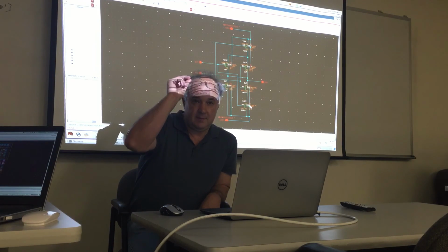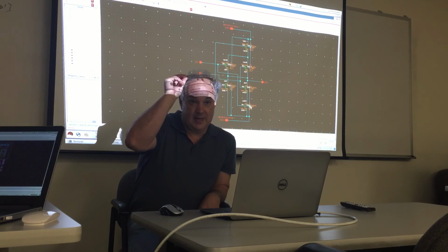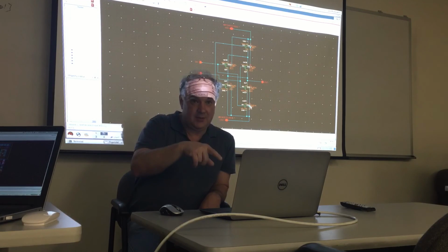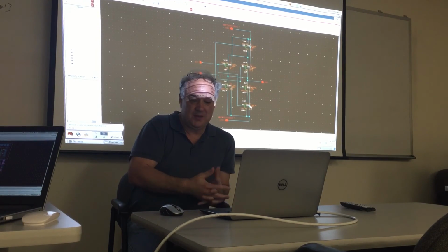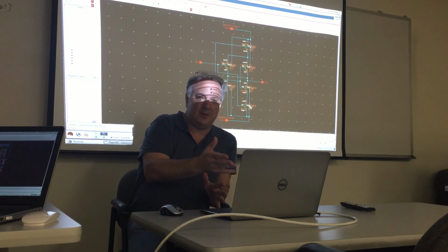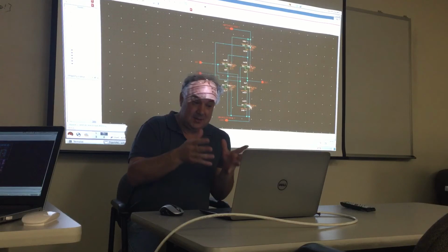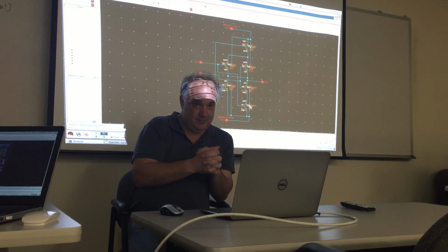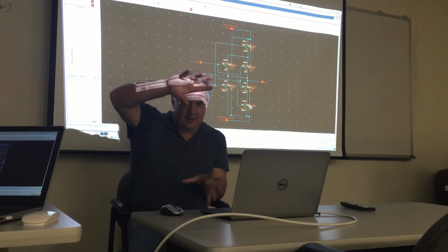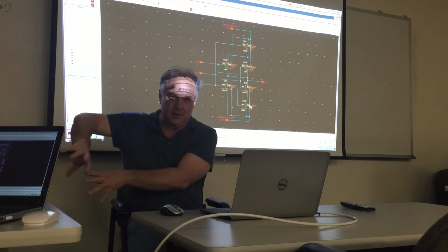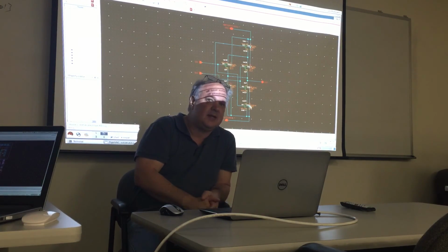No? Where is the inverter? There's no inverter here, it's an AOI, so you can't use this one. It's AOI, and-or-invert, naturally inverting. I did the hard ones. Because, like I said, this is a monolithic cell, there's no inverter here. It's naturally inverting, right? And so now I got the entire guts driving the output, and so I have to play these games with the sizing.